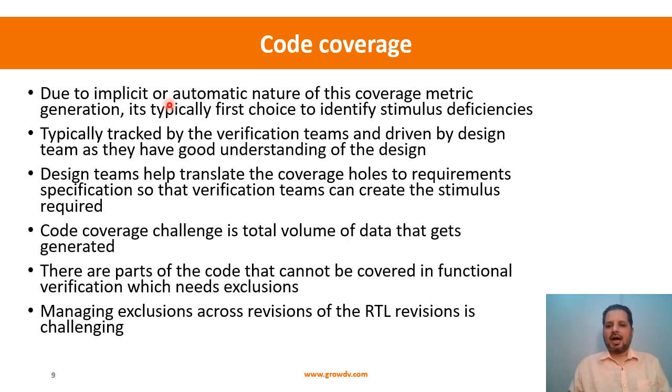So whenever you have code coverage holes, a verification team approaches the design team, and the design team helps them translate a verification hole to what exactly stimulus needs to be generated in the test bench, right? So they help do that mapping, and then based on that mapping, the verification team updates the test bench if required, or runs some specific tests, tunes them to target that area and to exercise it.